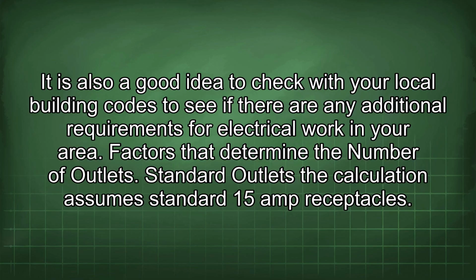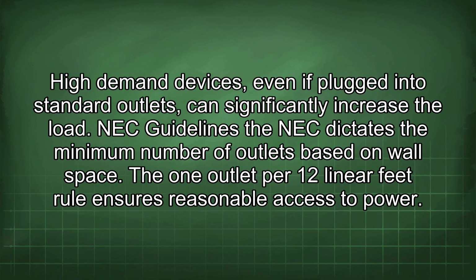Factors that determine the number of outlets. Standard outlets. The calculation assumes standard 15-amp receptacles. High-demand devices, even if plugged into standard outlets, can significantly increase the load. NEC guidelines. The NEC dictates the minimum number of outlets based on wall space. The 1 outlet per 12 linear feet rule ensures reasonable access to power.